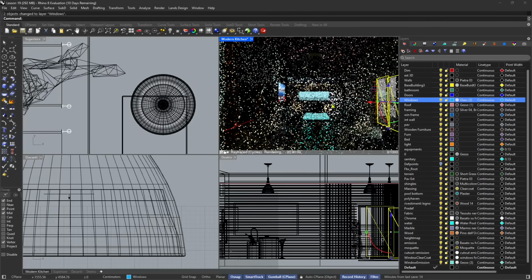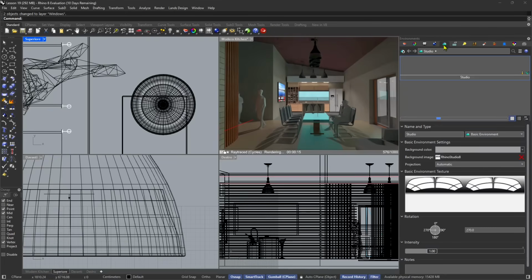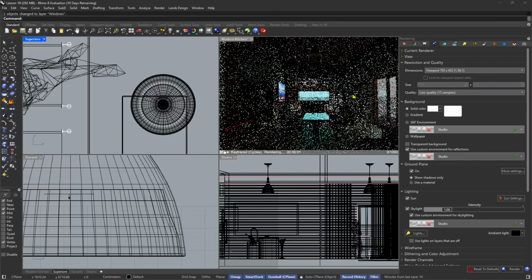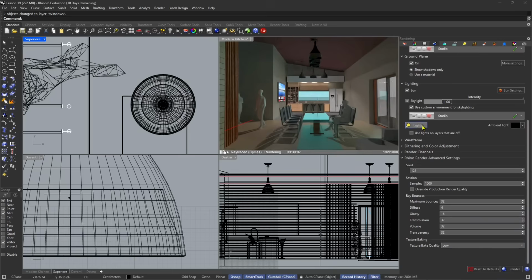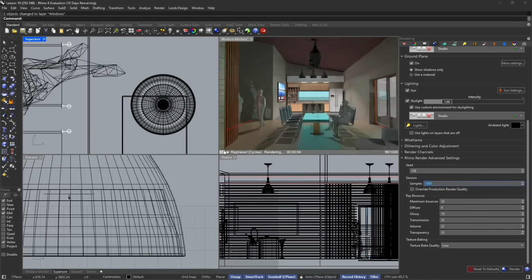1.52. And now let's take care of the exterior, because we can see the exterior from the interiors in this case. In other cases we don't, but in this one yes, so we need to fix it. And so we're going to go and use here the environment. I think I'm going to go to low quality now to continue to render, but quicker. So I can handle the lines from here. Samples, let's put 30, and so it's going to be quicker. Okay, less defined but quicker.